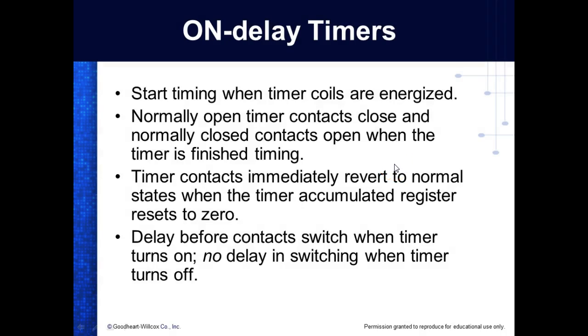On delay timers start timing when the timer coil is energized, or in our terms, when the rung becomes true, right? Normally open timer contacts close, normally closed timer contacts open. And this is what's nice about a software timer: you can make as many normally open and normally closed timer contacts as you need.